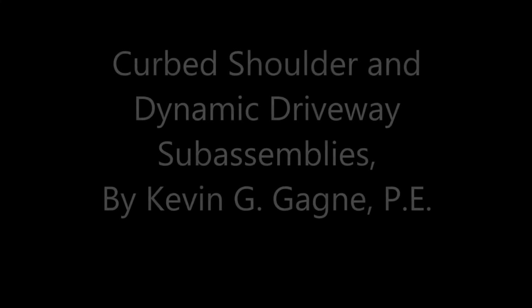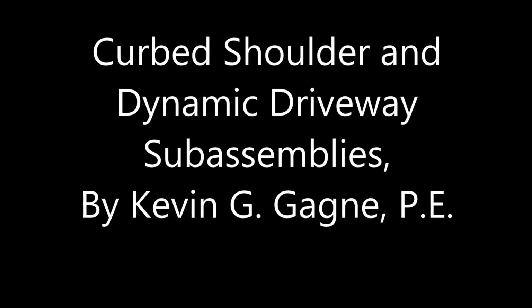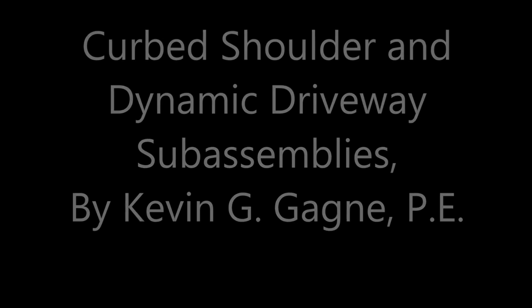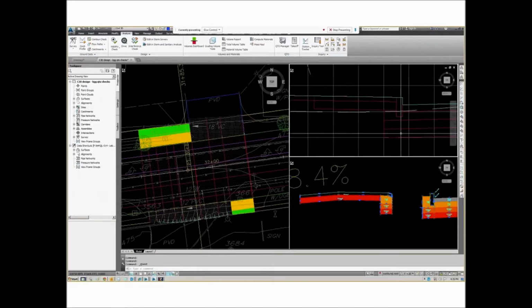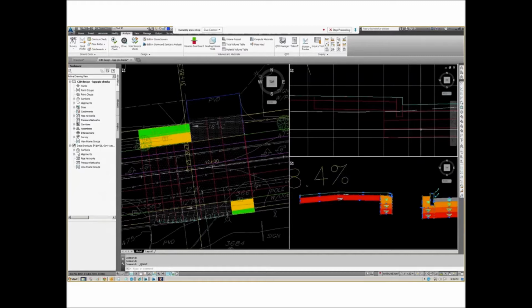So here I'll do a quick walkthrough of two sub-assemblies I made for the purposes of more efficiently designing municipal roadway projects in Civil 3D. The intent was, one, to be able to minimize manual drafting on cross sections, so that we can get the assemblies to appear exactly how we want them to be in the finished product, something that we couldn't successfully do with the assemblies that Civil 3D provides out of the box.